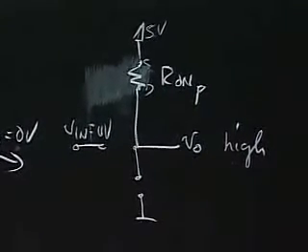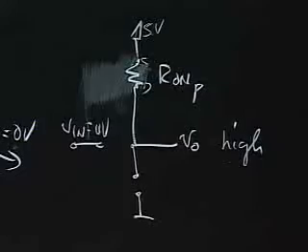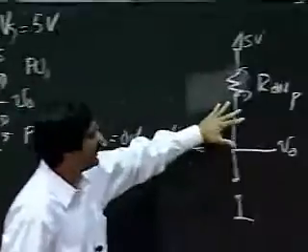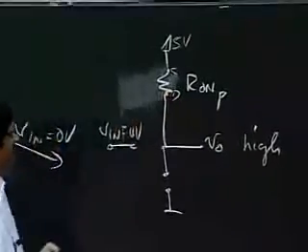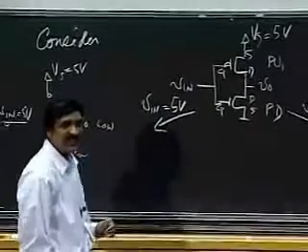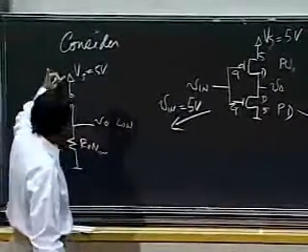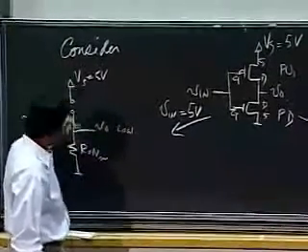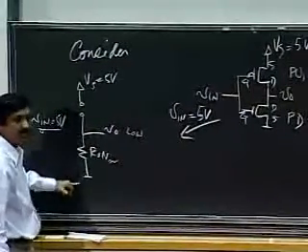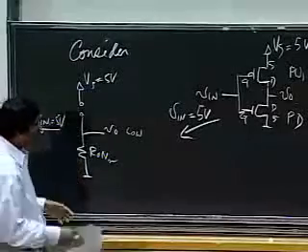So all I've done is replace my resistor with a complementary device, which switches off when the input is high and switches on when the input is low. And the beauty of this is that at no point, assuming all devices are ideal here, do I have a short circuit between the output, or a current path from the supply to ground. Okay, I have this turned off or this turned off.